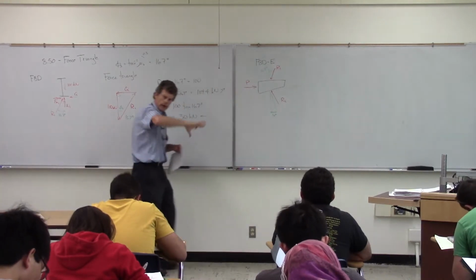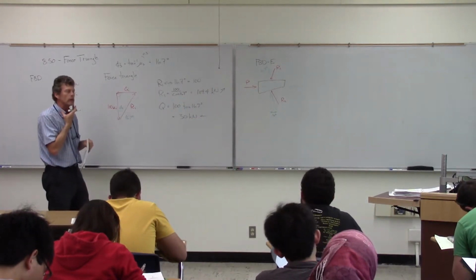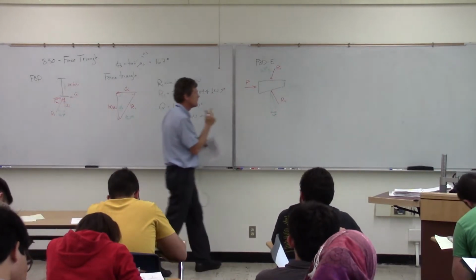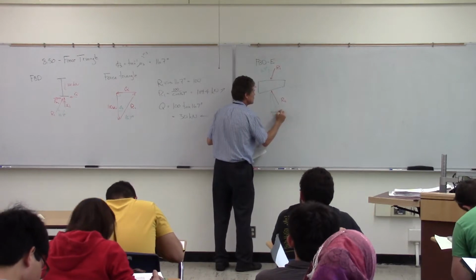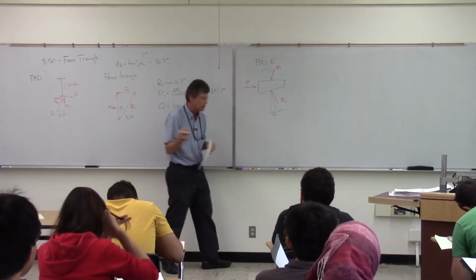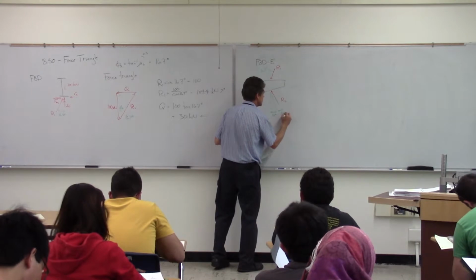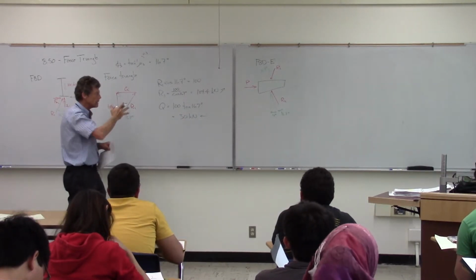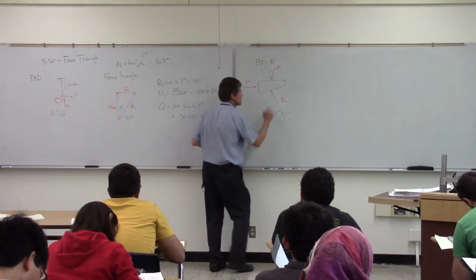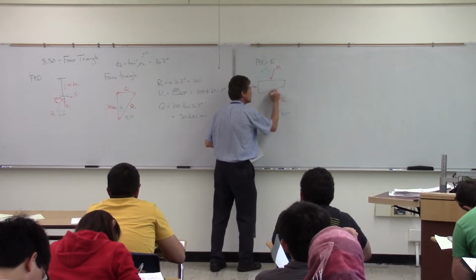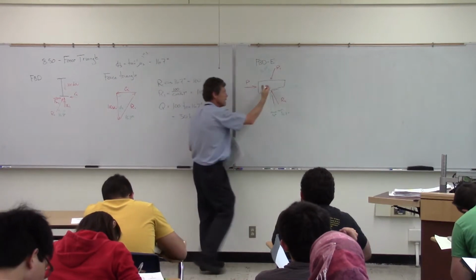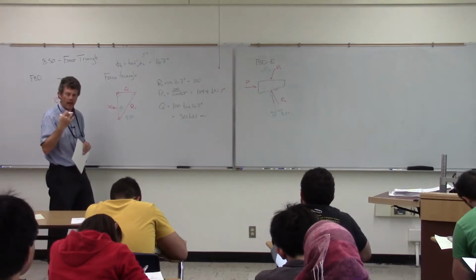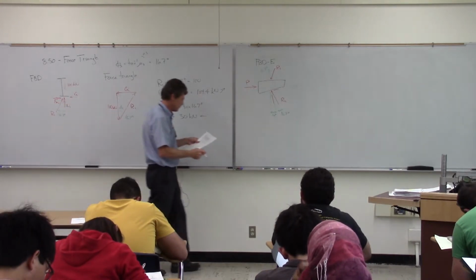It's already rotated over counterclockwise by 10 degrees because of the angle of that. And since the coefficient of friction is 0.3 on this one, we also have the 16.7 degrees there. If I were to draw it in terms of a normal force, the normal force would be going that way, and the vertical friction force would be going that way. So what I'm doing is now rotating my R2 over by that same friction angle of 16.7 degrees.